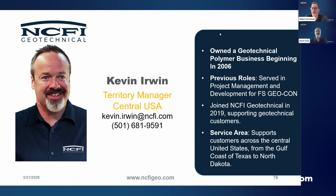Compaction versus permeation grouting. What factor is the driver for choosing each method? It's really the type of soil. You're not going to be doing permeation grouting in your smaller particle soils. So it's something like 3% passing a number 200 sieve, that's pretty much your limit for acceptance on some systems. It depends on the viscosity of the system, but it's mostly soil type, and it's also your goals for the project and honestly what you have with you.